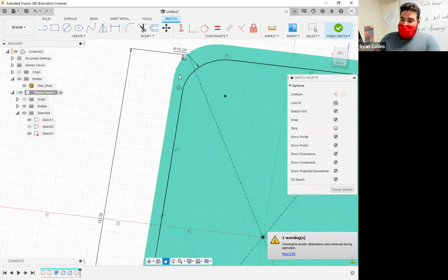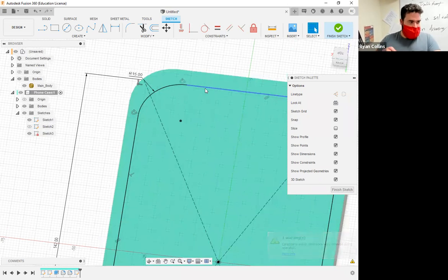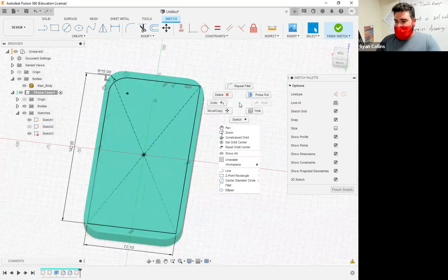So what you can do, instead of having to individually add fillets and keep selecting the appropriate dimension, if you mouse over where it says your radius, R15, what appears is D11 colon 15 millimeters. The D11 is because fillets are created off of a circle in there. So what you're seeing is the diameter of that. So D11, cool, okay, keep that in mind.